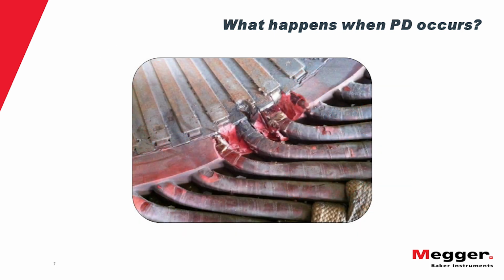Voids can also form in the insulation system as the motor ages. This will cause partial discharge to develop later on in the life of the motor, driving it toward failure more rapidly.